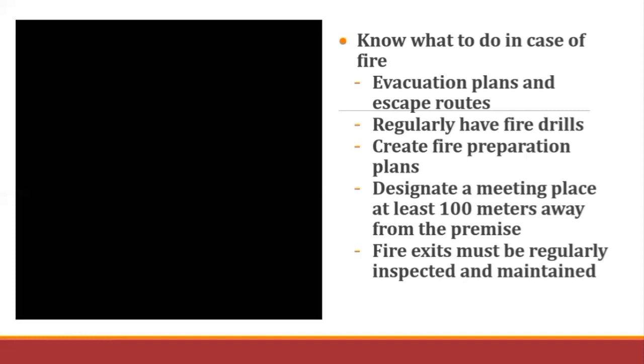They must also conduct regular fire drills. Make sure there is a time assessment. That is needed, you can't just be strolling around. We have to take it seriously when we participate in fire drills. Create fire preparation plans. Designate a meeting place at least 100 meters away from the premises. Then fire exits must be regularly inspected and maintained.